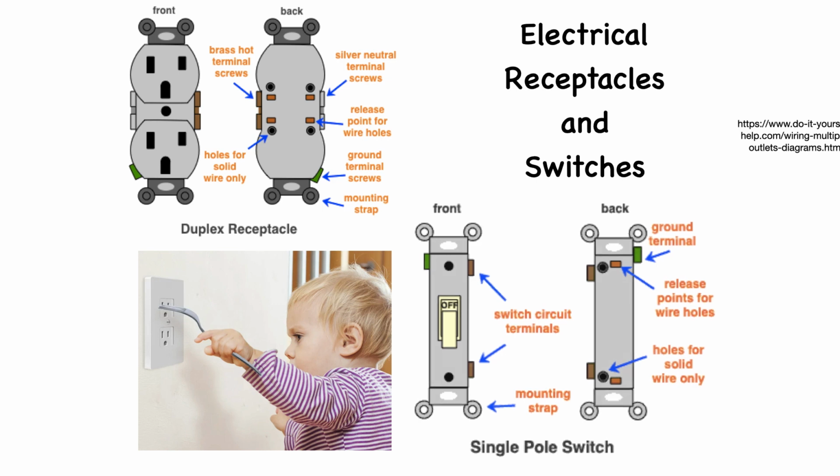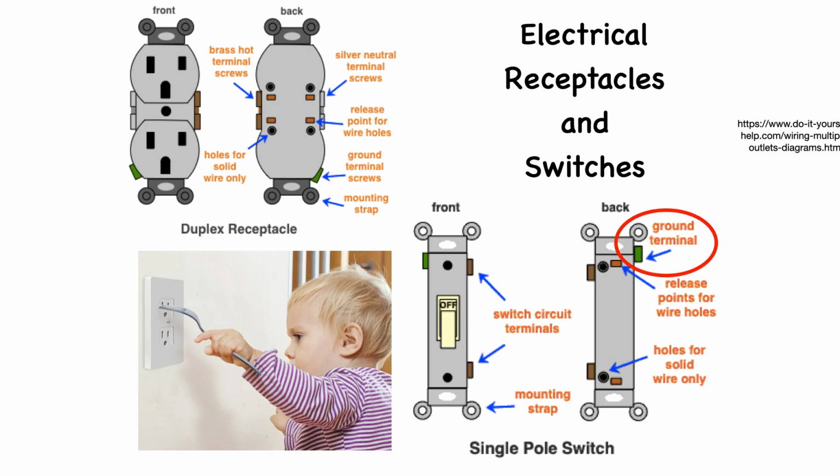An old switch can be replaced with the same type, or you can change a single pole switch to a rheostat dimmer if it controls approved lighting fixtures. Older switches may not have a grounding terminal, and there may be no ground wire present in the switch box. In these cases, if it's a grounded metal box, the grounded terminal on the new switch should be connected to it.